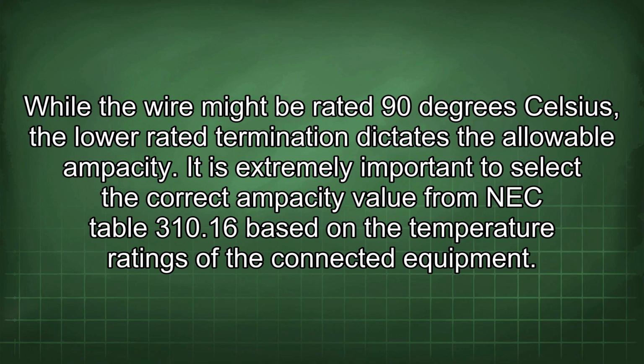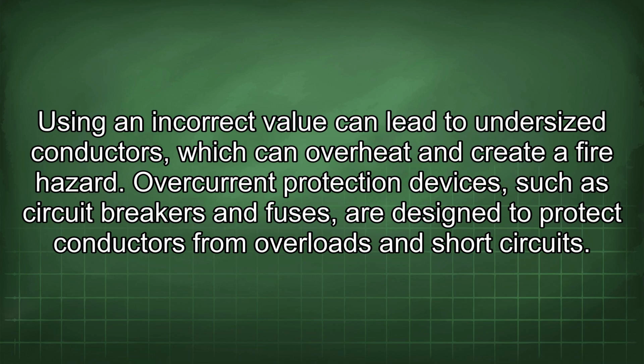It is extremely important to select the correct ampacity value from NEC table 310.16 based on the temperature ratings of the connected equipment. Using an incorrect value can lead to undersized conductors, which can overheat and create a fire hazard.